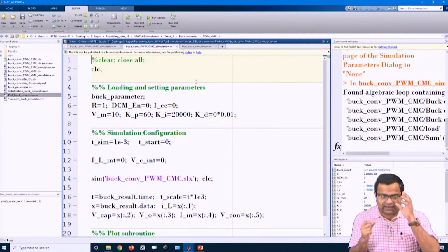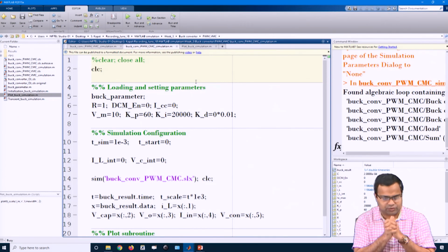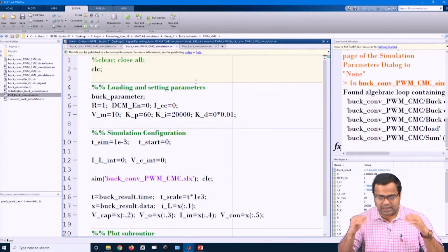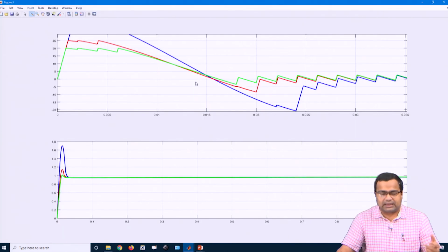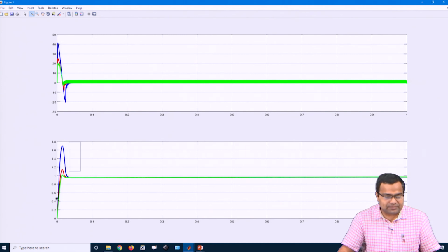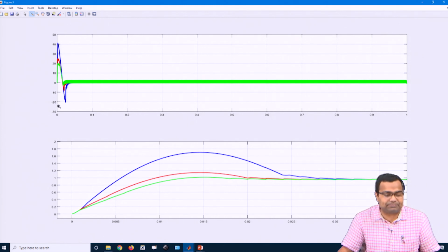Okay. So now what I did, I just put a current limit, in fact, there is a closed feedback loop. So there is no problem, and I have decreased the current limit from 25 ampere to 20 ampere, and this is my response. So now you can see the startup performance is significantly improved. I can set the peak current limit up to the nominal load current.